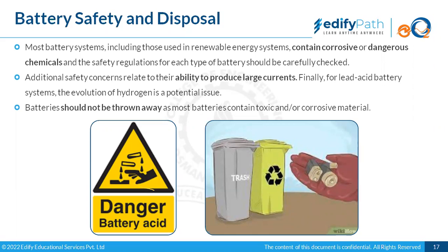At times, we have seen conditions where a battery has caught fire. If it has caught fire, we extinguish the flames with the help of, say, a fire extinguisher. There is no flame or smoke coming out, but if that battery is kept unattended or not properly disposed of, it can again catch fire, because it is still in abnormal conditions. Any cell can again initiate the fire, the same condition. So when either it has fully burnt or it has entire material, nothing is left in.